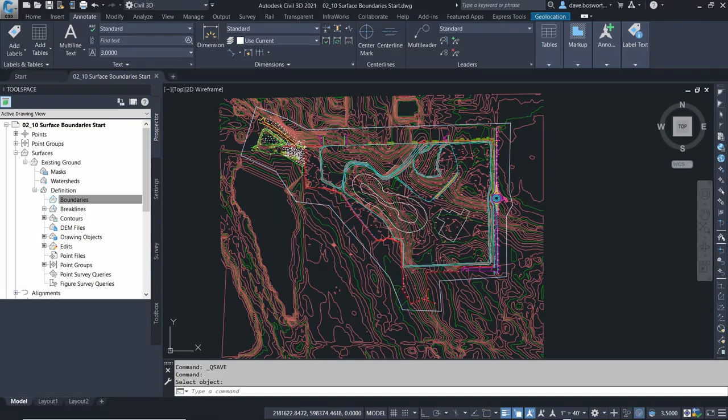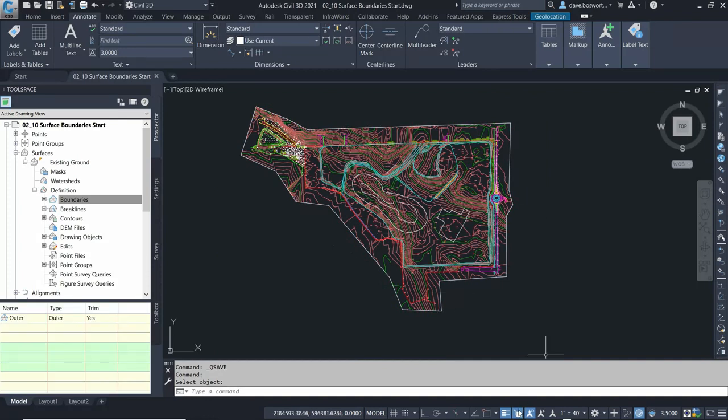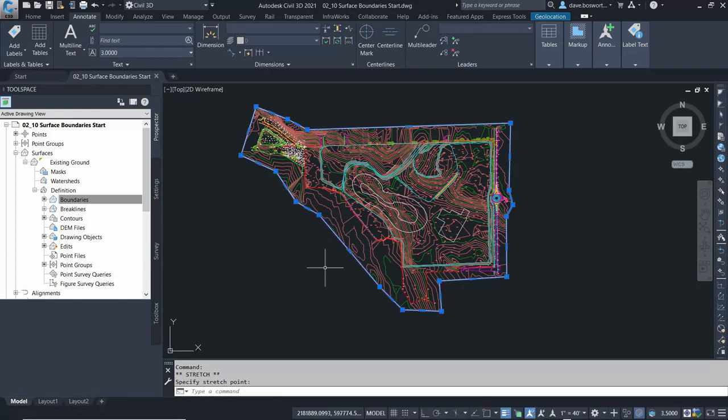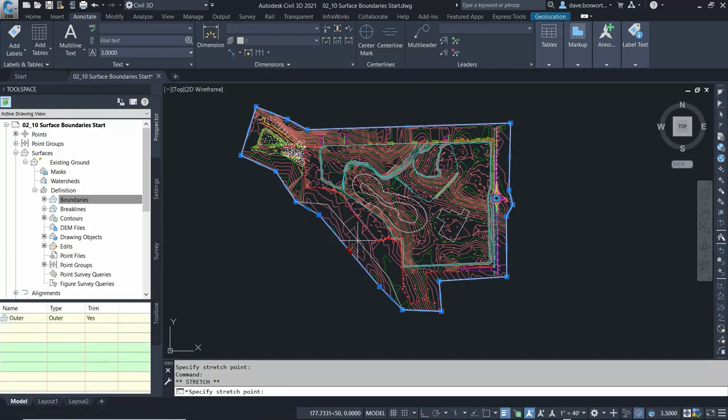The polyline remains linked to the surface. If you delete it, then you're deleting the surface boundary, and the surface will revert back to its original size. Use grips to edit the boundary. When you change the polyline, the surface rebuilds automatically and resizes to the bounding entity.